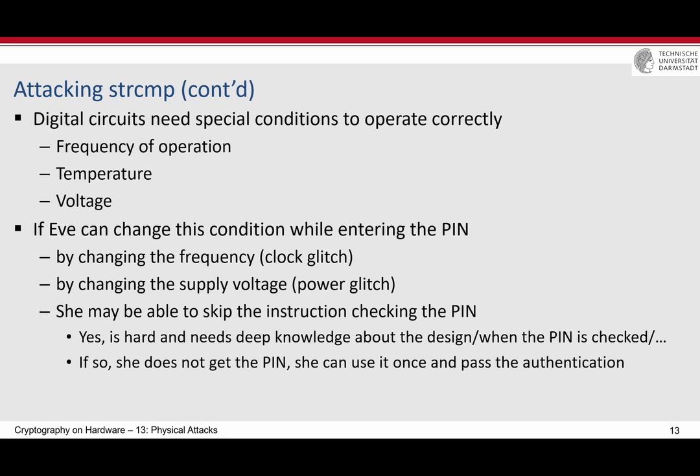There are many other schemes, I mean, these are simple scenarios, but there are many other schemes to provide security against fault attacks. But again, the security against these fault attacks also depends on the adversary model. For example, even if you have 2 instances of the AES close to each other, you can imagine that one attacker injects 2 laser faults into exactly the same gates, and then they produce the same output, and the output is also not true. But it's the same in both cases, so the fault passes through the check. Again, it depends on the adversary model. If you assume that this adversary model is not a valid one, then your implementation might be considered secure.